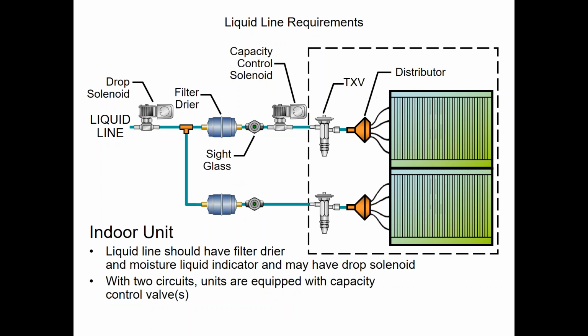Most all the equipment, especially chillers, is oversized nowadays. This is plain and simple fact. They're oversized, and some grossly. So you're never going to get that machine to a full load state, not even at 95 degrees in many cases, to charge by chart.